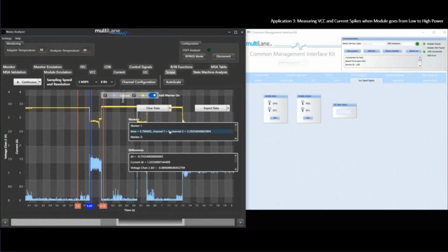So sometimes voltage drops can really affect high power modules going into high power mode, and you need to compensate for the drop. But again, compensating for the voltage can sometimes be dangerous if there is no voltage drop, which is again why we need a measurement tool to do that.